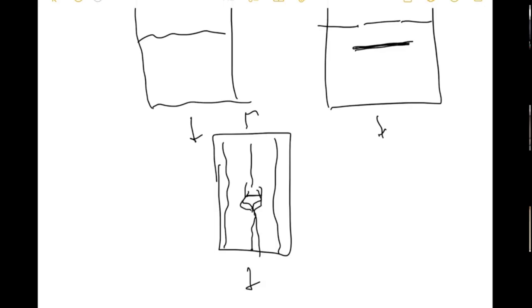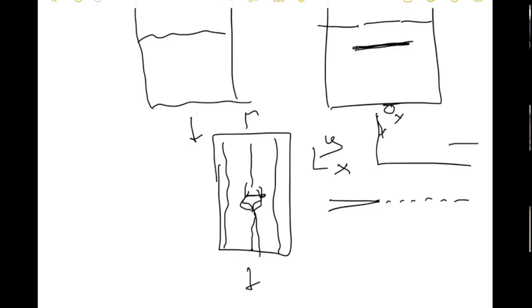And it turns out for a crack, the theoretical stress at the tip, if you plot, this is X, this is Y, you plot sigma Y along this line, far away it's equal to the applied far field sigma. As you get closer, it goes like this, and it actually is an asymptote to infinity.